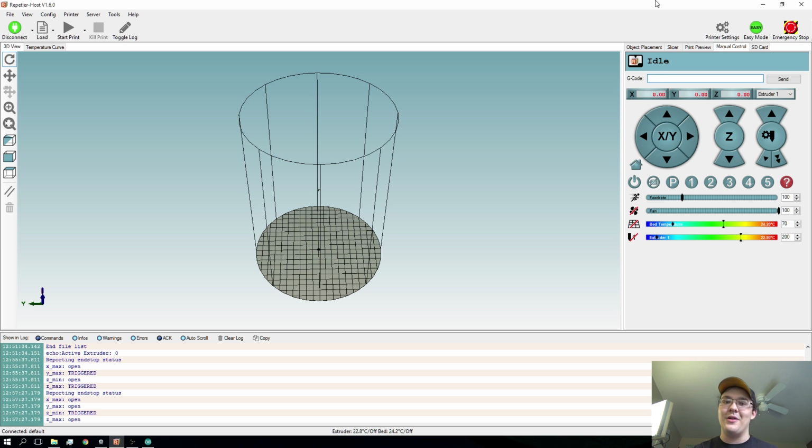Okay, this is important. You don't want to screw things up. If the end stops are correct, it should be alright, but if the motors are reversed, if something's going wrong, something was wired wrong, the motors are spinning in reverse, or the programming you didn't change for the motor direction inversion, something like that, this is what you're going to need to do, is hit that button.